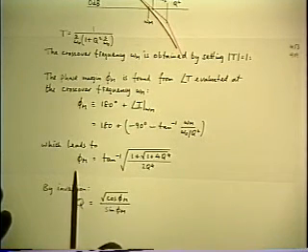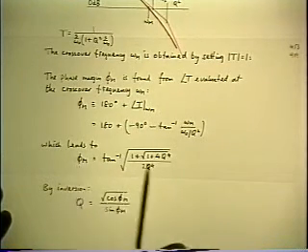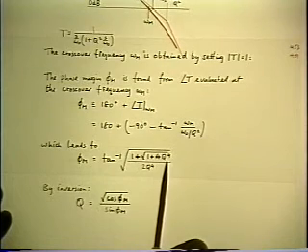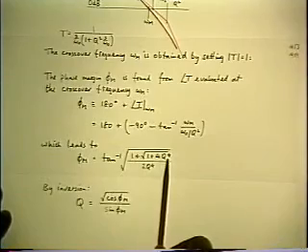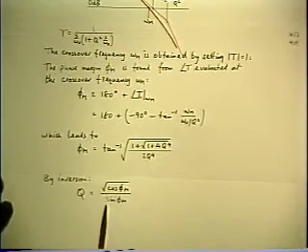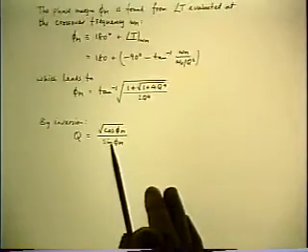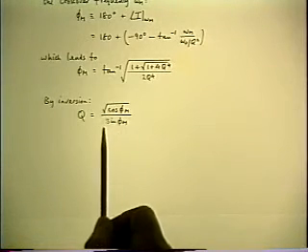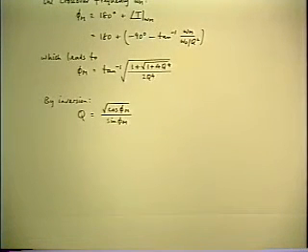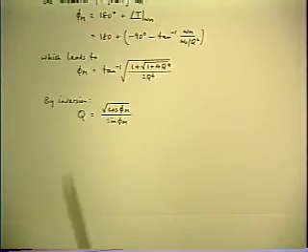So this is the relationship between phase margin and the peaking factor of your closed loop gain. And you can invert that expression and get this one. And that's the bottom line. Now, you don't learn much by looking at that equation. You learn a lot more by looking at the graph of that equation.